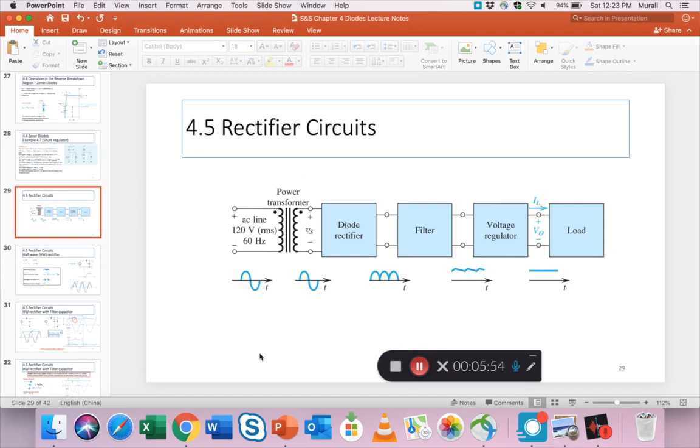So the diode rectifier section generally doesn't give you a smooth DC. Now the goal is to get, when we say DC, we assume one constant line, right? That's the best type of DC. Normal rectifiers put out a pulsating DC. They are DC, they are on one side of the axis, they never go down to the negatives, but they're not a solid straight line type DC. They tend to be like half AC waveforms, right?